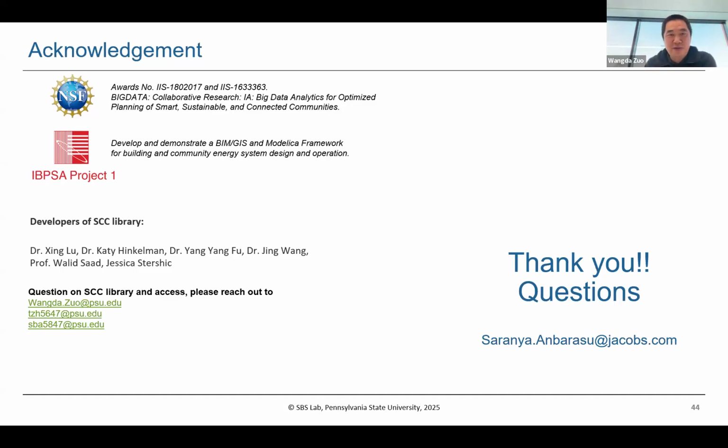Yeah, just for your information, if you're interested in taking advantage of Python, there's two options. One is using BuildingsPy. It's also developed by LBL. It's part of the Modelica Buildings library. That allows you to use a lot of Python functions, then connect to the Modelica model. But in that case, you have to have your Modelica software running, executable. Another option is to export your Modelica model as a functional mockup unit executable. Then you can call it directly using your Python code. So that's two options. We are using both of them in our lab.